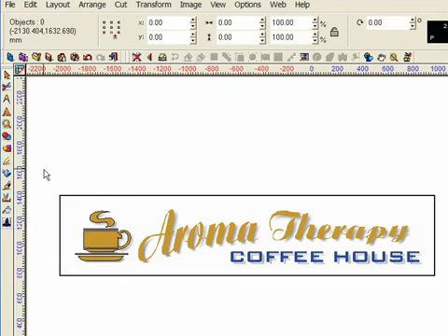After all, a design that's just plonked in the middle of an A4 sheet or on a computer screen will not explain the size, dimensions and materials to be used on the job. To add that professional touch to my visuals, I will use SignLab's Dimensions and Notes tools. First I will select all the objects on screen and then group them together by going to the Layout menu and selecting Group.